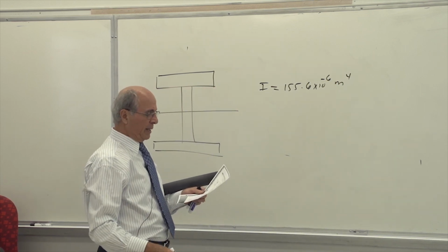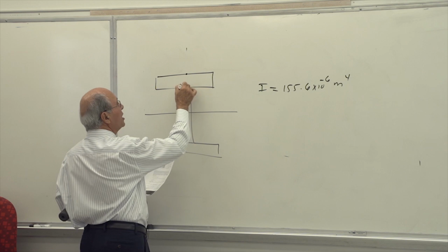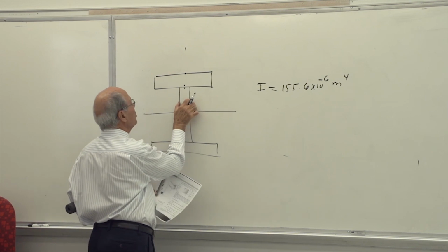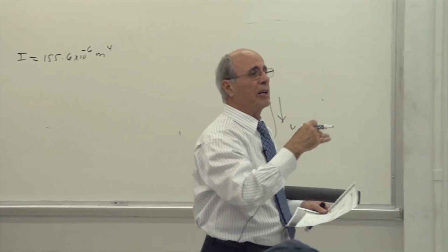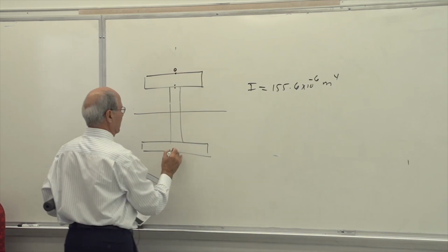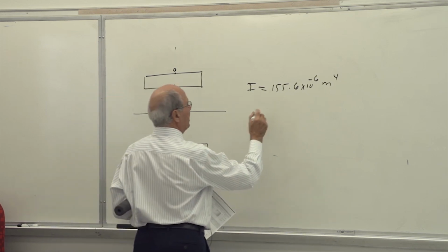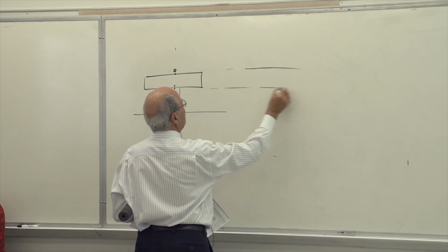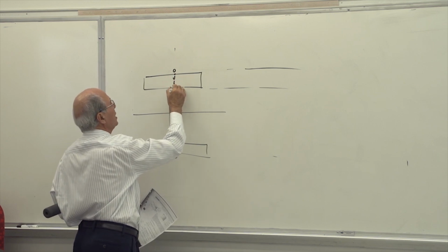Yes? But then they are asking you to calculate shear stresses here, here, here. Why here? Because there is a little bit of change. Actually, there is a lot of change here, because this thickness versus this thickness has a ratio of 10 to 1, 15 to 1. Therefore, as I go down, here is 0, first of all. Here is 0. In between, I have to find the shear stresses. So as you can appreciate now, I'm going to erase that and use this, again, the distribution. The shear stresses are here. Everybody see that? Yes? Start here, 0, keep increasing.